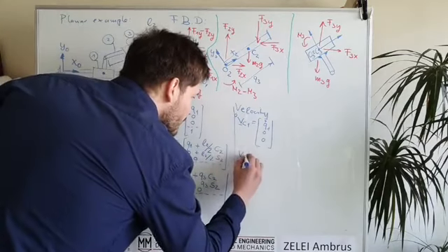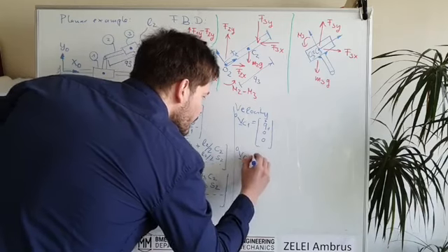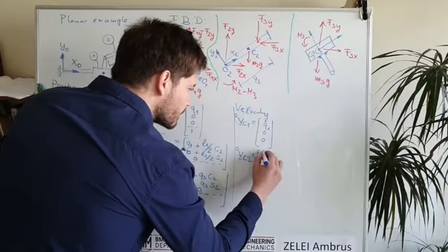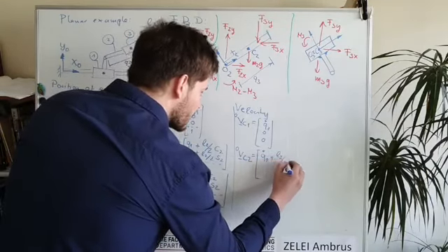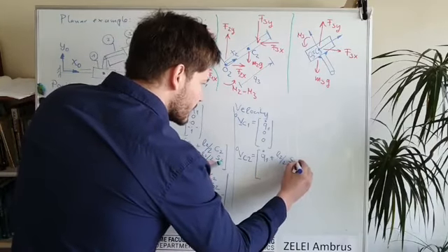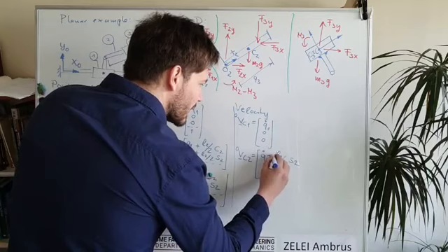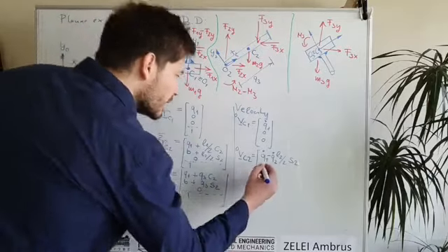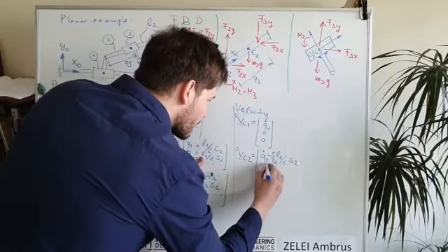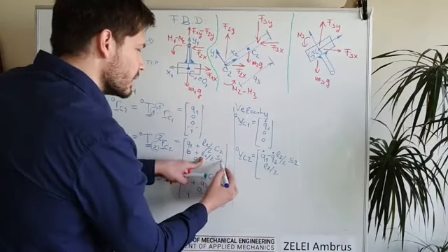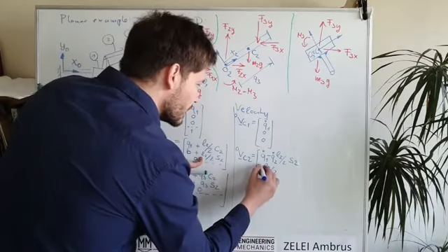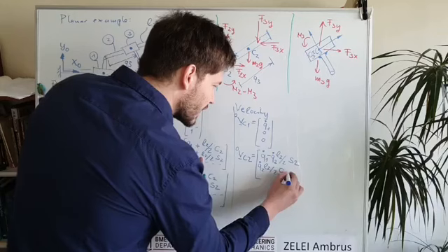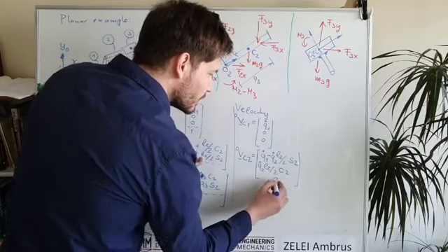And in case of the second, we will have, for example here, Q1 dot plus L2 over 2 times sine Q2, but this is minus, and there is minus, and there is also Q2 dot because of the chain rule, and then the time derivative of B is 0, and we have L2 over 2 times the derivative of sine Q2, which is Q2 dot times cosine Q2 because of the chain rule.